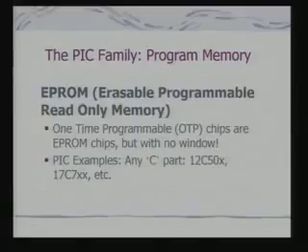When we are doing mass production of an embedded system, the software development cost goes into NRE, that is non-recurring cost, and after that I simply write that program onto the EPROM and produce a chip, and that program is not expected to be changed ever after. These are particularly intended for very low cost applications. So when you buy a PIC processor, you should look for C. If there is a C in its number, that means it has an EPROM as program memory.